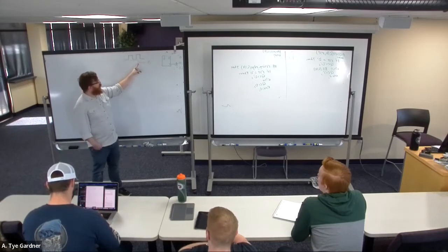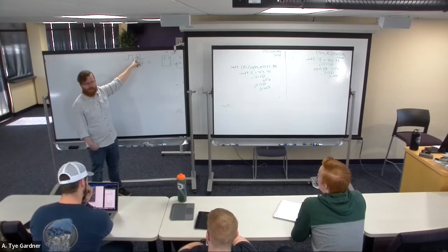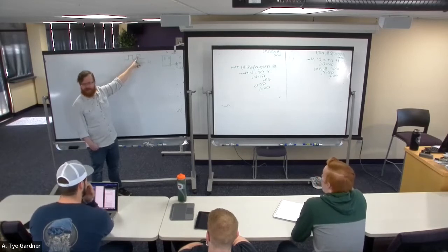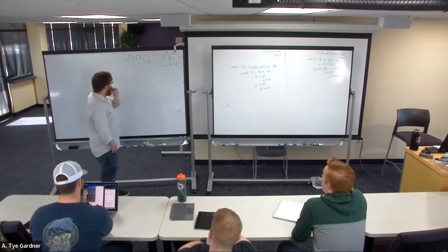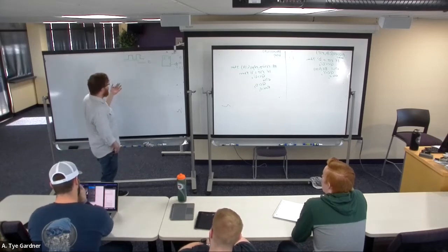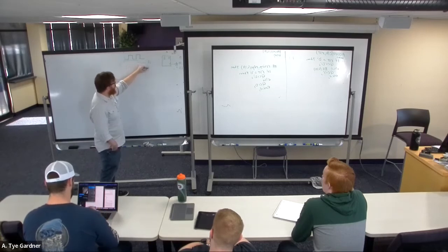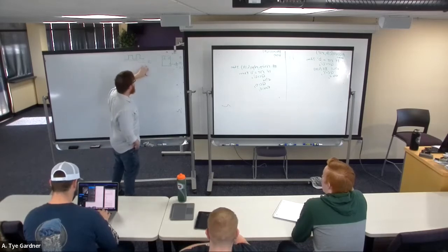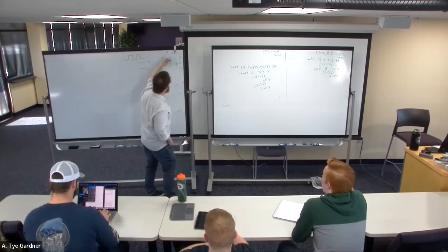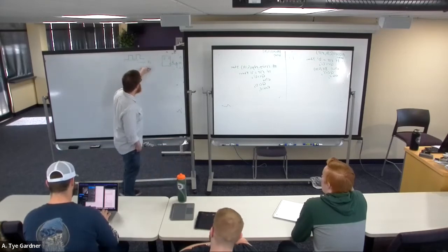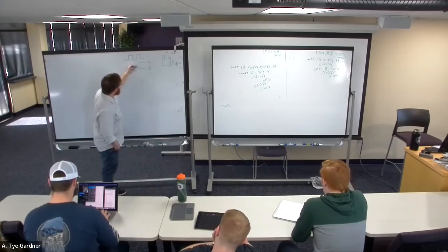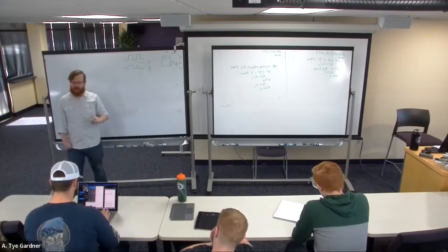But then the CE turns on here, and I get a rising edge of a clock in the middle of the clock, which is not really good, right? Because what's just happened is, well, we've created the output, well, not Q. Let's call that signal N. N is going to do something like this, where it's going to get a little flip in an otherwise good clock.